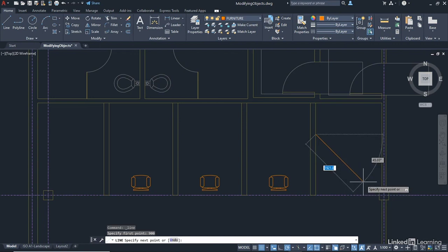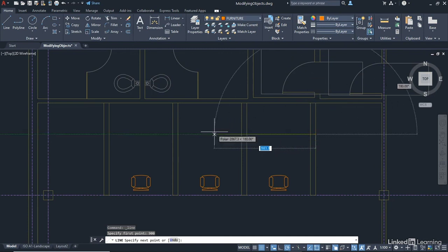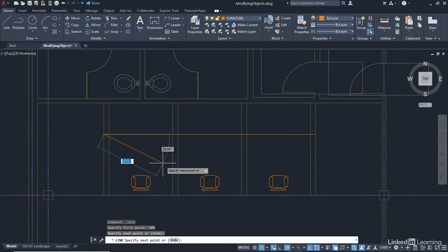As you do that, can you see your line now starts 900 down from the original point that you hovered over? That's all to do with your object snap tracking, your object snaps, and your polar tracking. Now, we're going to utilize polar tracking to literally go all the way across. Can you see the green dash line? As long as that green dash line is there and you get that intersection on the other side, we're going to click like so. Now, if I click there, can you see an orange line all the way across? Press enter to confirm that.